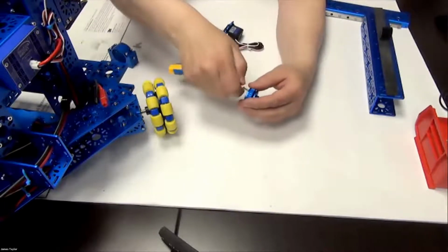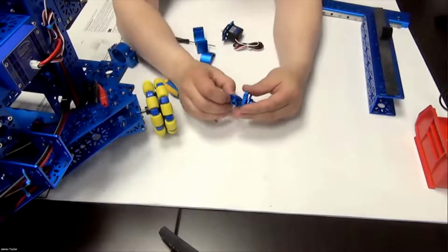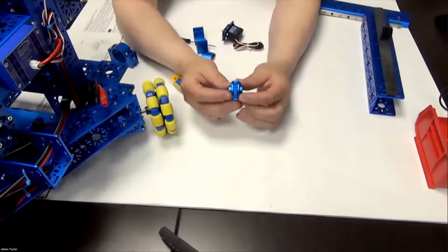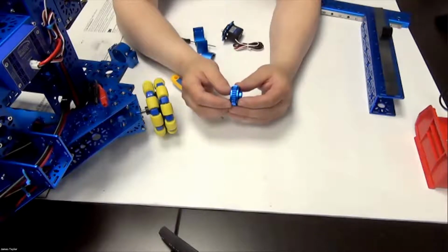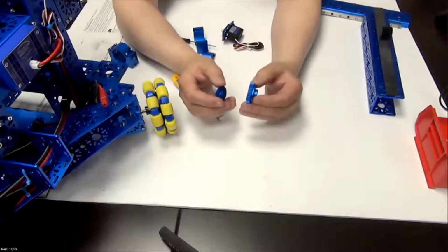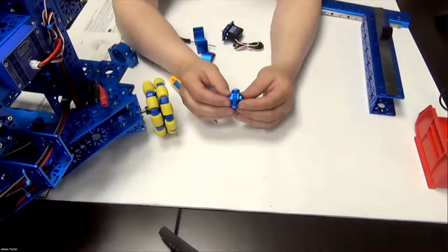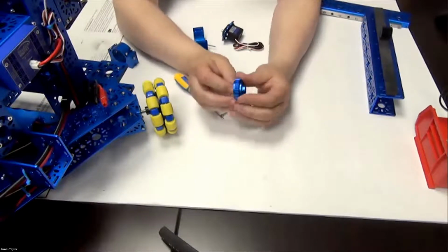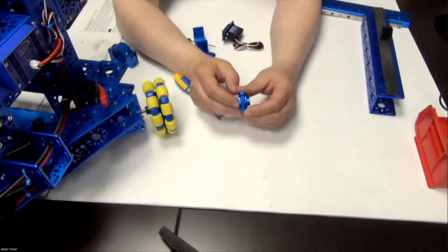Am I saying that you need to do this? No, because remember that it may look like a small component to you right now, but every component that you add adds to the complexity. So you could do it this way, or you could do it this way. It adds to the weight of the robot, which may throw off your center of gravity. But if you think it's a critical part and you're worried about a slippage or failure, then you can add 2 shaft hubs either that way or that way to provide more strength on a critical gearing system.